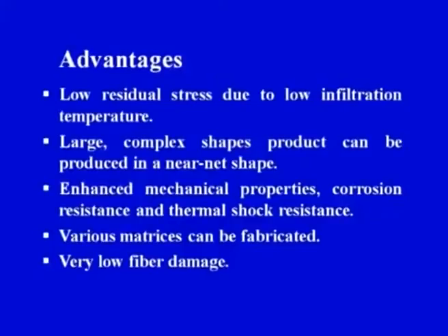Now let us see what are the advantages of this process. First and foremost, as we have a preform and the gases are being passed and the reaction product or the solid is being deposited on the fibers, we are creating the matrix material and blending the matrix and the reinforcement together to get the composite material. So there are low residual stresses due to low infiltration temperature. The residual stresses that are developed are lower in case of the CVI process.